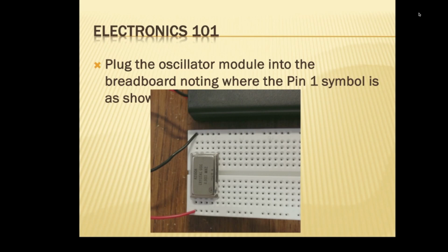Okay. Ready? Okay, we're not getting something there, so let's back up just a minute. Let's go back to the output. Okay, we got our square wave. Okay, so the module itself is working. Put out 3.9996, which is close enough to 4 megahertz. So we're doing good there.